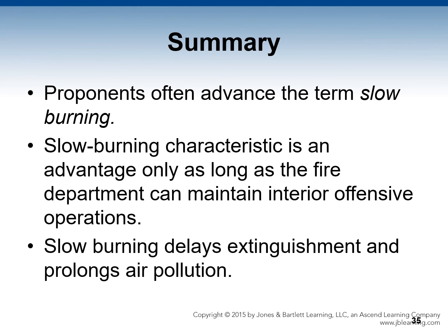Proponents of heavy timber construction often advance the term slow burning as an unqualified advantage because of collapse resistance, when in fact the slow burning characteristic is an advantage only as long as the fire department can maintain interior offensive operations, provided they get there quickly enough. Once the fire department must operate defensively, slow burning delays extinguishment and prolonged air pollution can occur.